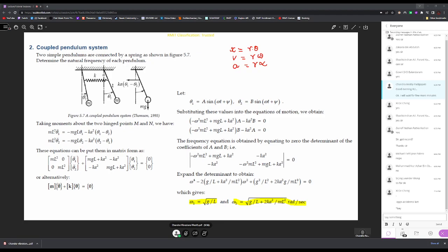From the free body diagram, to get the equations of motion, we apply the same concept. Because here we are dealing with angular displacements, the net torque acting on the system must be zero, or the torque due to the forces must be equal and opposite. So what is the torque? Let us take the first mass M1.